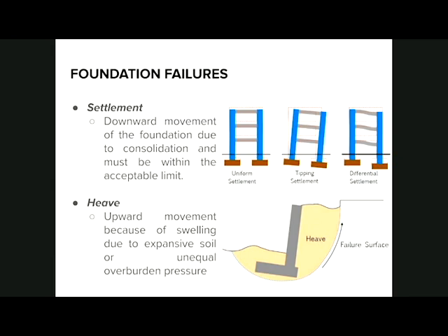To reduce the settlement, we also reduce the possible increase in stress of soil due to loads, by setting an acceptable depth of our shallow foundation. For a foundation to be called shallow, its depth must only be up to the projected dimension.